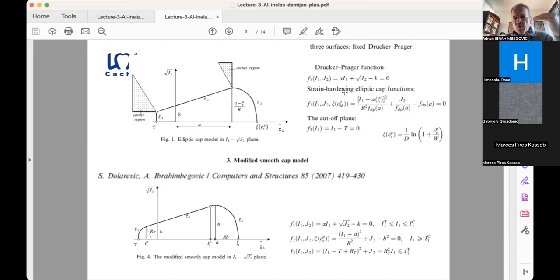If you want to generalize Mohr-Coulomb, which is kind of one-dimensional, to a three-dimensional case, you replace cohesion with the square root of J2. This is the square root of the deviatoric part of stress. And you replace normal stress with the first invariant of your stress tensor. And then you adjust the coefficients accordingly. Now you get this line, which is given by the angle of internal friction and cohesion, to handle the sliding of this material, like soils and stuff like that.